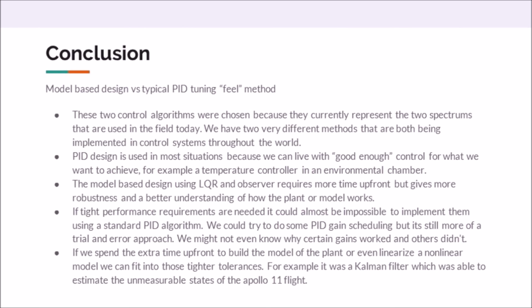So in conclusion, we would like to briefly summarize the advantages and disadvantages of the two different controllers we designed. In terms of robustness and efficiency, the model-based controller, which is controller 1 in our case, designed using an LQR-based observer, is more robust and faster than typical PID controllers, which is controller 2 in our case. In terms of cost and time, model-based controller design is costly and requires more time to establish, but it is reliable and works on a control algorithm and sets up a lot of mathematical equations.